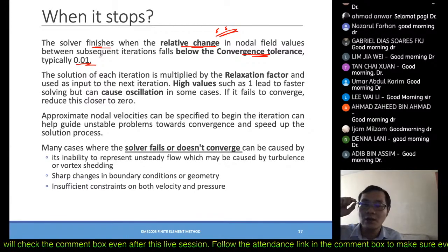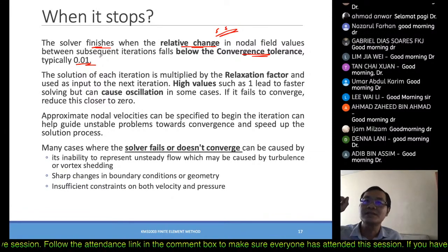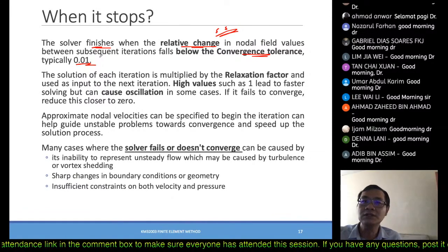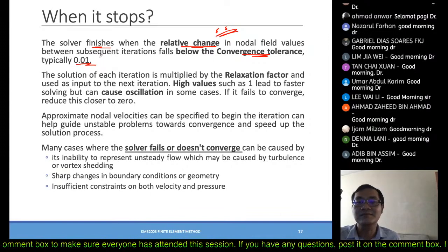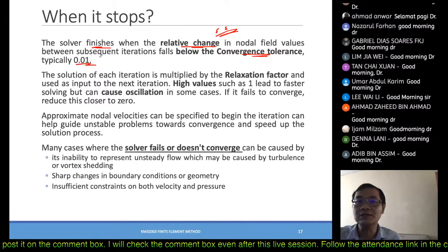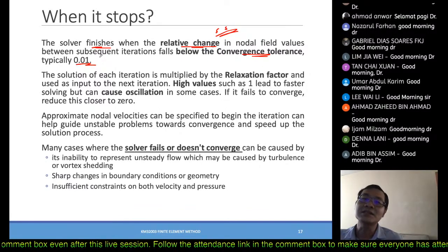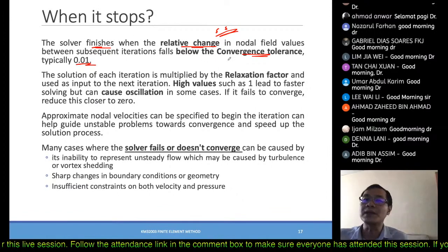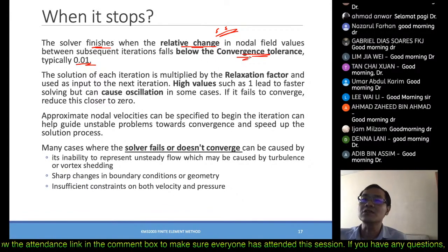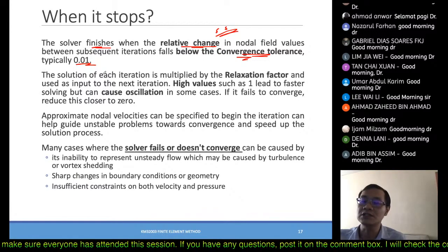So that's why with a different computer, different time, same finite element model, when you run it and look at the decimals at the back, sometimes it is different, even though it's the same model. This is because of these stopping conditions. They do iterations, and when it reaches this condition, it just stops.